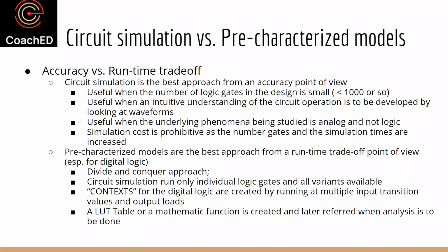Only for very special circuits, or when people are doing very detailed and specific analog simulations, do they go ahead and accept the extra run times and run circuit simulation. But usually for digital circuits, people avoid running simulations unless it's a very high performance circuit or your tolerances are very, very tight.